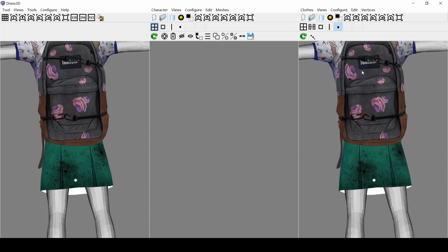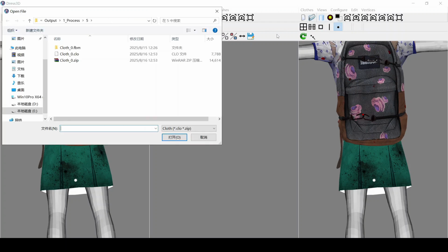And then let's attach the rod to the dressed cloth. So click Open and here change it to Static Models and go to Input Rod Select. This one, no change.